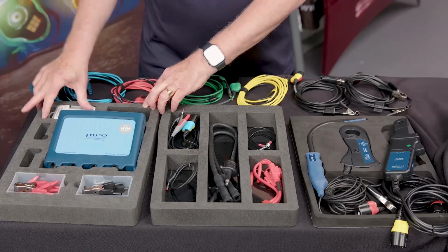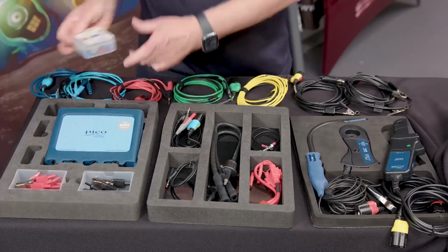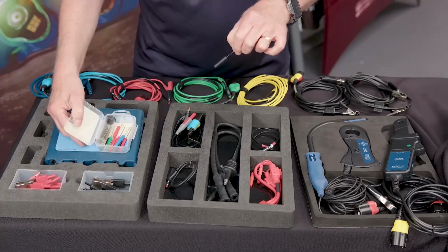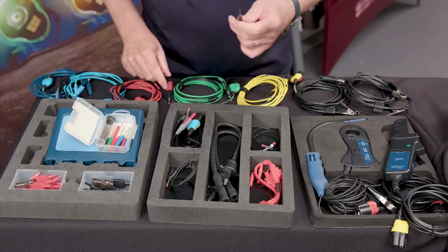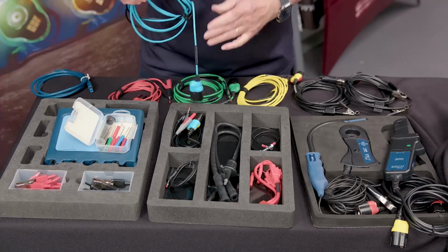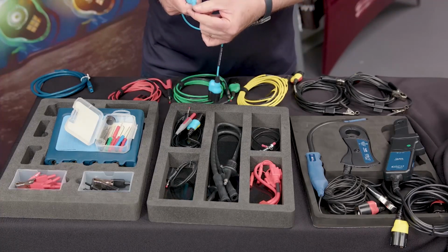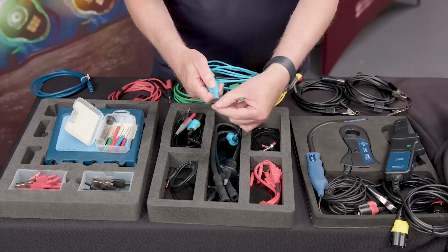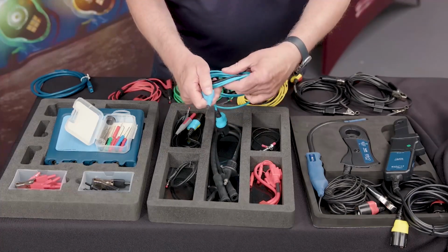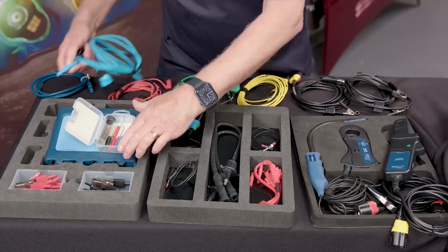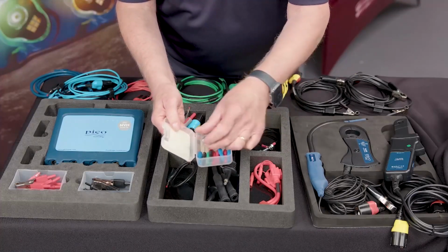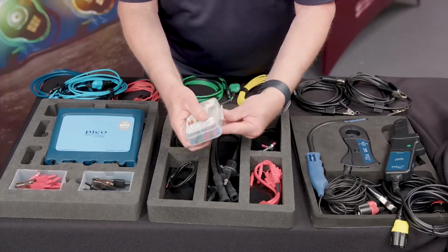The majority of the time we are going to use a backpinning probe. So what we're going to do is connect that onto our test lead, like this. And we're going to go down the back of the wire, on a wire, we're going to push that down the back of the seal on the plug, and we're going to make connection. So again, we have all the different colours, and we have replacement needles inside, so that when they break, you just put them in. So that's the first way.